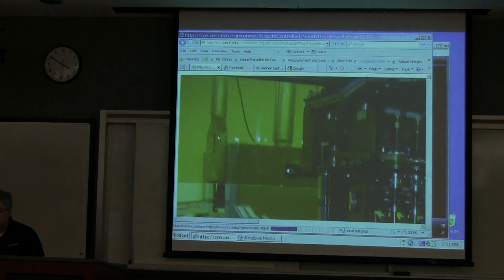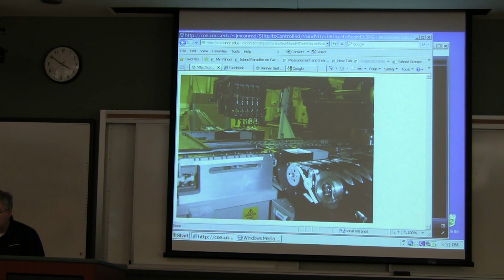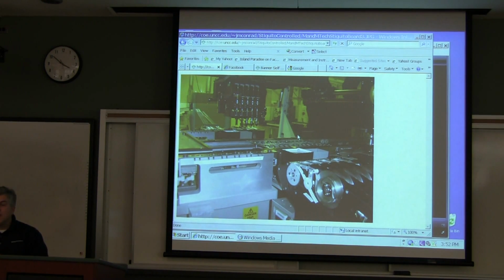There's a picture of the manufacturing in this movie, and to give you an idea, here is a printed circuit board. It's in a robotic pick and place machine. So you feed it with instructions. This is a camera right here. It has LEDs which will shine up, and then these devices right here are actually air grabbers. Using suction air, it'll pick up parts from reels right here, and it'll place them on this board. They stay on the board because this board is covered with a sticky solder paste. You've probably seen solder in the little strings, right? You have to melt it. Well, you can have paste that has the same composition as the hard solder that you use with soldering irons. Then you run the paste through an oven, and it will bake the parts on that you place.